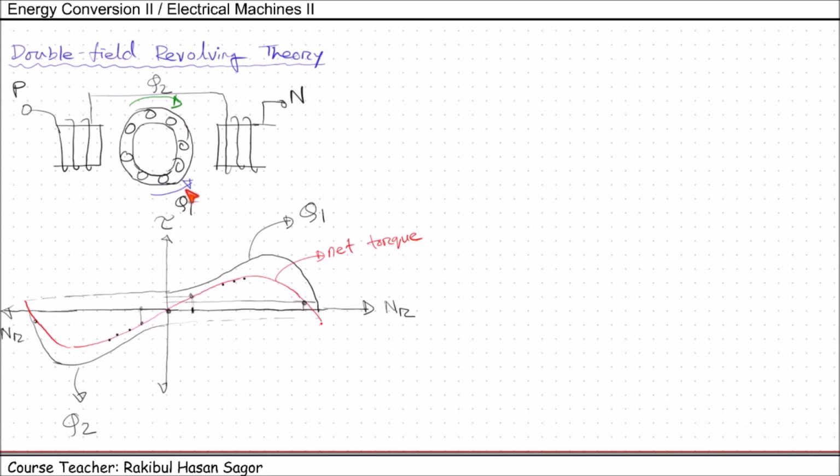In order to do that, we can split the phase. We have a single phase supply. From the single phase, we need to make multiple phases. First of all, we'll try to create two phases from the single phase supply. That feature is called splitting the phases. Before I start that topic, let's see how a rotating magnetic field is created from a two-phase supply.